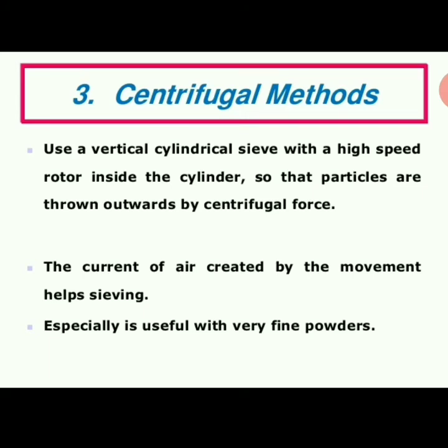Also it is extremely useful for fine powder because sieves have the limitation of mesh size. Okay, sieve have the limitation of mesh size, so we use the centrifugal method for the proper size separation. Then this is all about the centrifugal method.